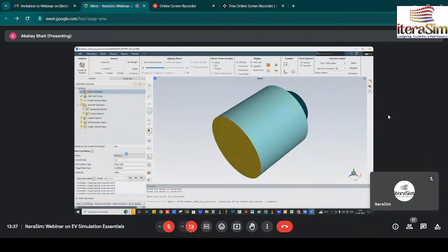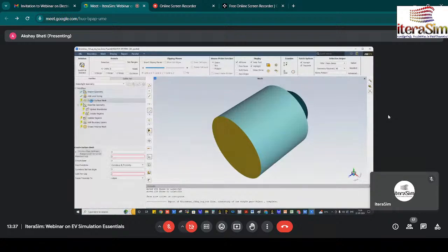As we were discussing, face sizing and local sizing, we can give local sizing directly to any body. Different parts are coming, so we can give local sizing anywhere. And here create surface meshing. We can give surface meshing anywhere, and scope proximity to faces and edges also. There are some gaps between the bodies, so we will put two cells per gap.